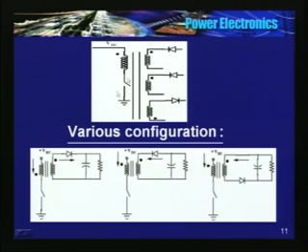So, when I close the switch, energy is stored in the primary. No current is flowing in the secondary because of these diodes. Open the switch, energy is transferred to these secondaries. So I can have a large number of secondaries now. I can have a positive voltage and a negative voltage, any number of voltages. So plus 5, minus 12, plus minus 5, so on, anything.